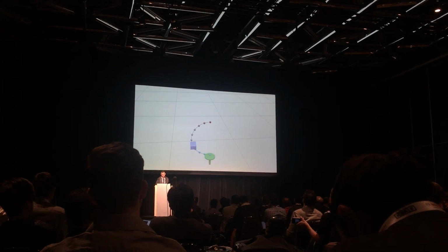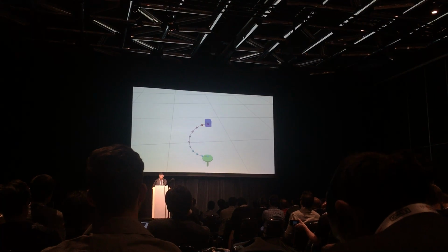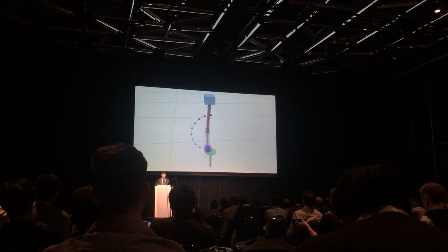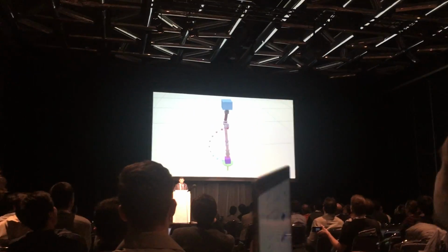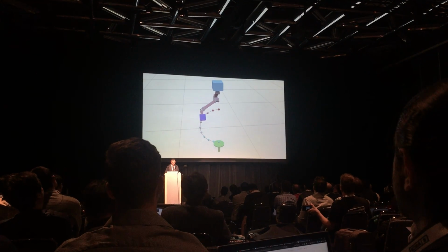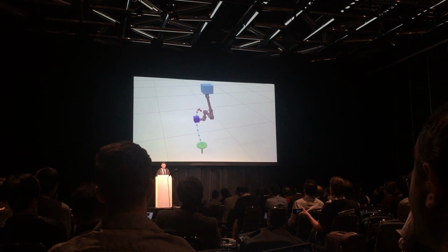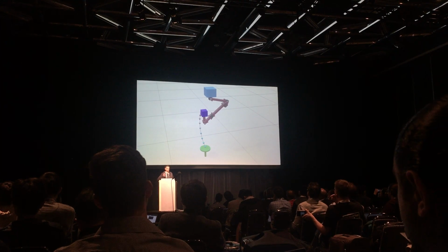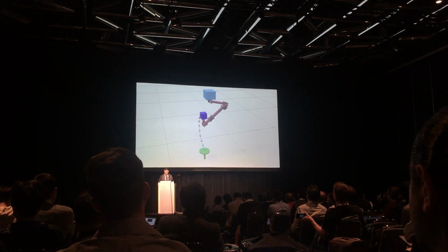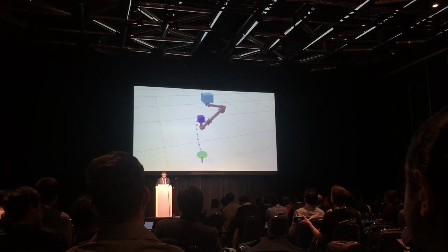So this example now shows the process of searching for solutions. So we have an initial robot design here. We're not visualizing the end effector, but what we're seeing is the motion planning problem that is solved for this hybrid design that includes the virtual end effector. And basically, after evaluating a very small number of possible designs, it figures out that this robot has enough degrees of freedom to solve the desired trajectory for the end effector. Now, this is a very simple example, and of course, we can make it arbitrarily more complex.